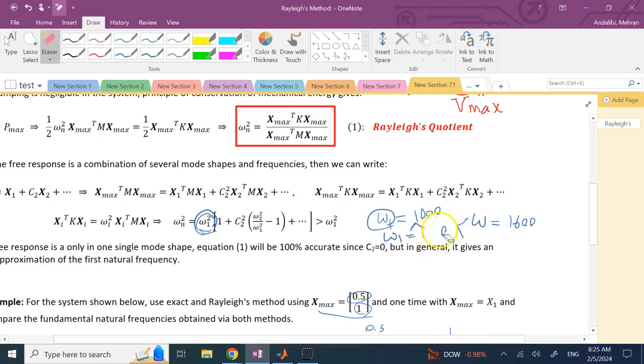But if Rayleigh quotient gave me an underestimate, so it gave me what? It gave me 700 instead. And I say, well, 700, I go above 700, no worries. I go to maybe 1000 or maybe 1050 or something, 1100, 900. Then I'm very dangerously close to my natural frequency. Okay, so it's better that it's overestimating my first frequency than underestimating, and it does that.